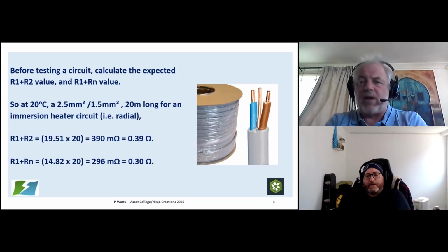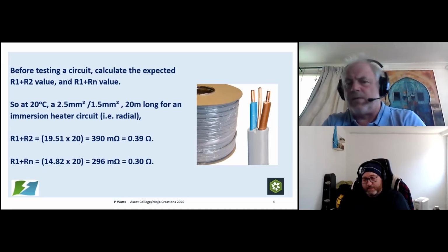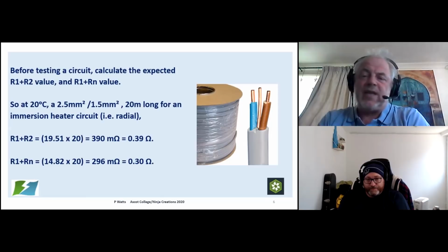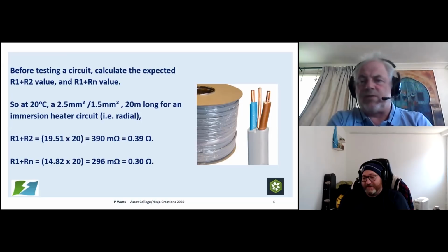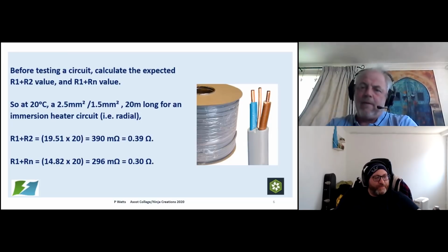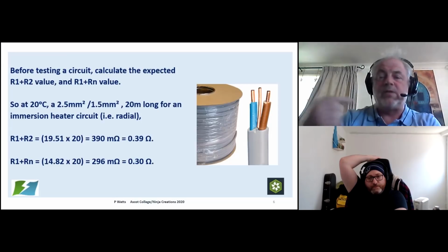I will still do these regular checks, and it's up to you how often you do them. I think in guidance note 3 they recommend every 2 months. What you've got to remember is that the longer you leave it between checking the accuracy of your tester, the longer it is that you've got to question all the test results you've done if it does go off accuracy. If you've left it for 2 months, you might have quite a few test sheets to go back to. And that's the point of putting the serial number on the test sheets. That's why we do it, so we can check what was tested with that tester.